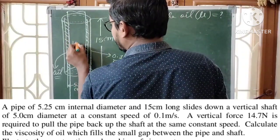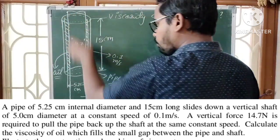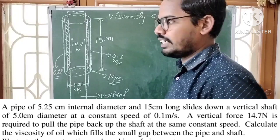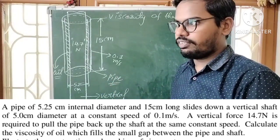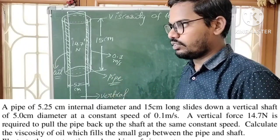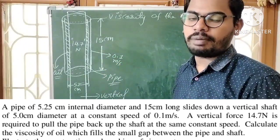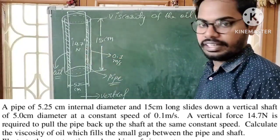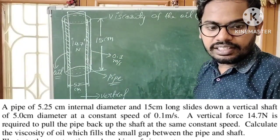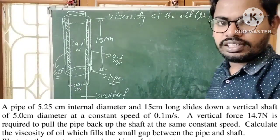Here we need 14.7 Newtons vertical force to pull the pipe back off the shaft. It means informally we can say that we require 14.7 Newtons vertical force to separate shaft and pipe. Okay, this much force we require. So ultimately we need viscosity of the oil. So how do we get viscosity of the oil?